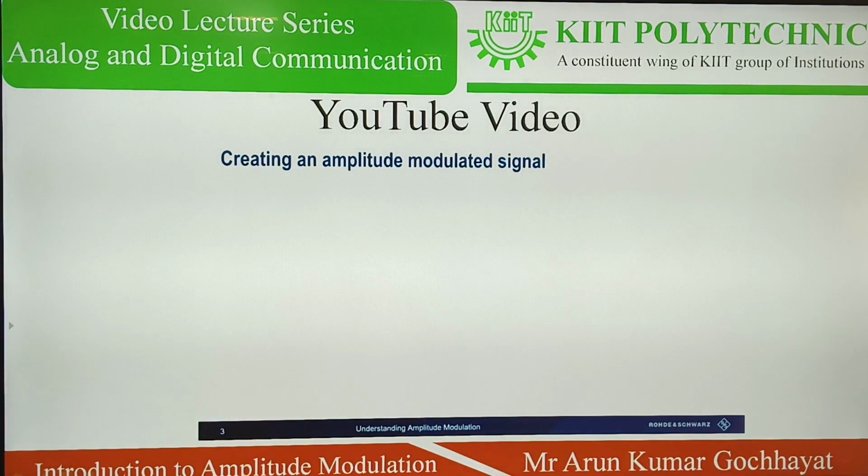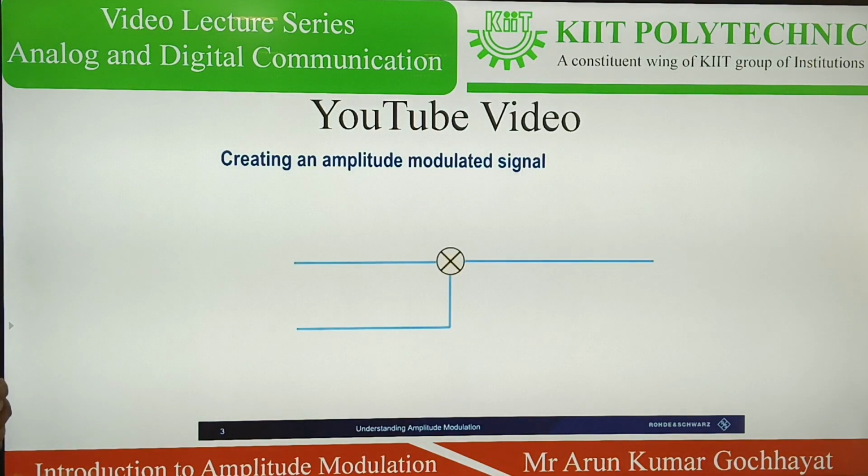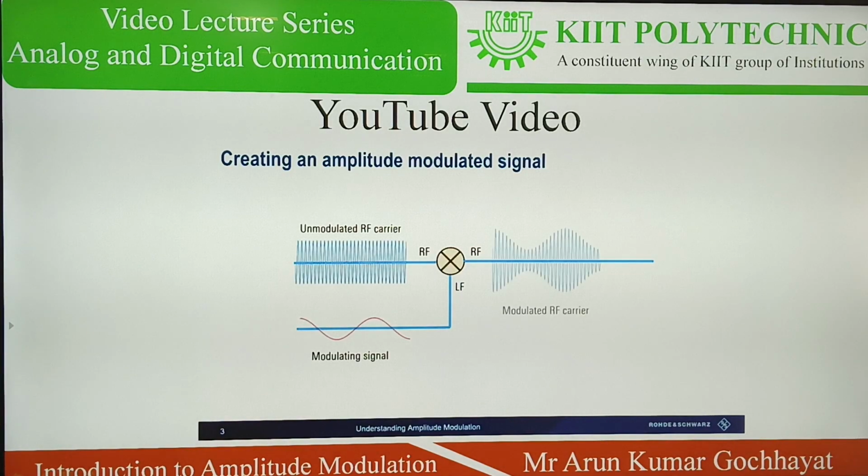How do we create AM signals? Most often, AM signals are created using a mixer, the inputs to which are an unmodulated RF carrier and a low frequency modulating signal. The result is a modulated RF carrier, whose time domain envelope is a copy of the modulating signal.